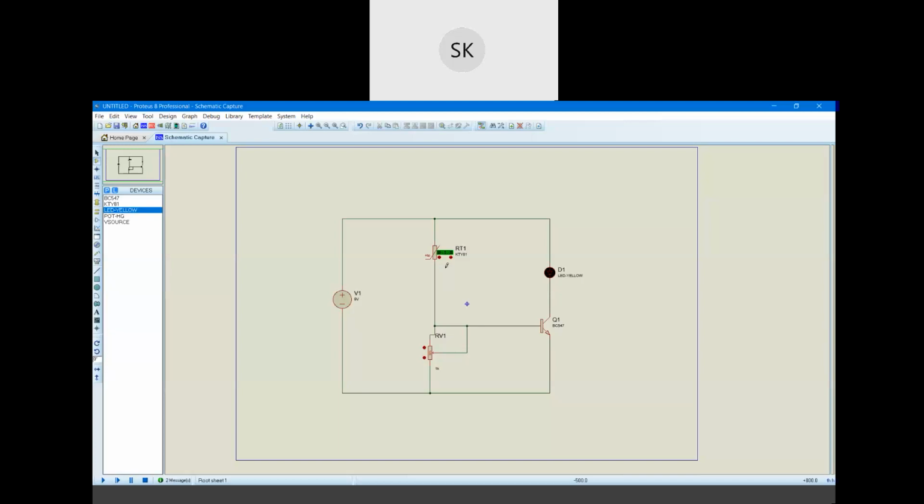So a thermistor is a resistor which varies with its temperature. If there is change in temperature surrounding the thermistor, then its resistance will change. If we see its graph, as temperature increases, the resistance of the thermistor decreases. So when there is rise in temperature because of fire, the thermistor resistance will keep on decreasing, and as soon as the resistance decreases, the base terminal voltage will start flowing. So this is how a thermistor relates with a fire alarm. Thermistor is used for changes in temperature.